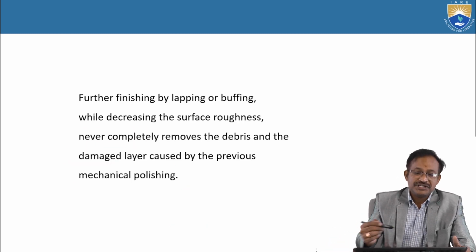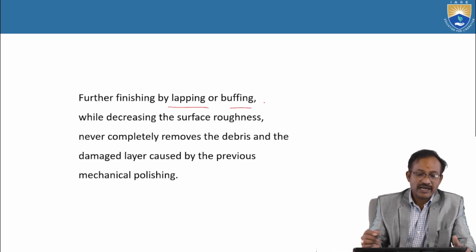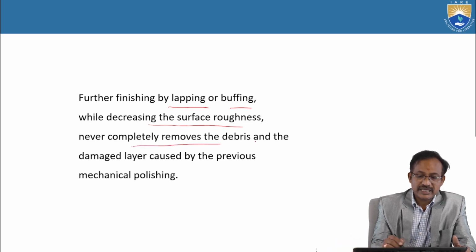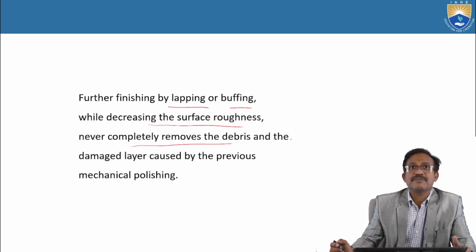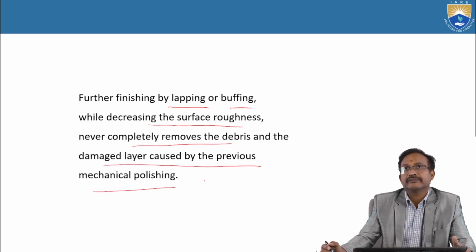Further, finishing by lapping or buffing, while decreasing the surface roughness, never completely removes the debris and the damaged layer caused by the previous mechanical polishing.